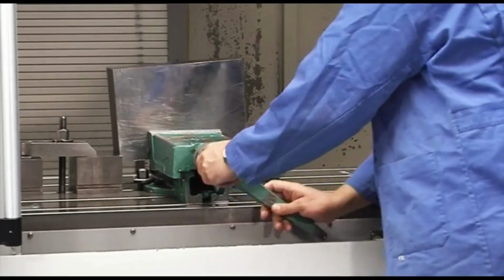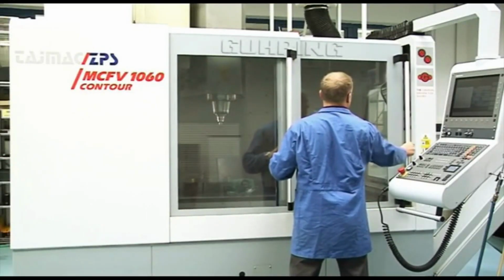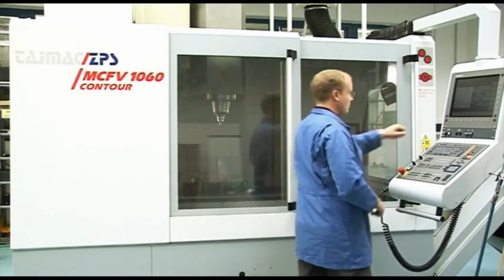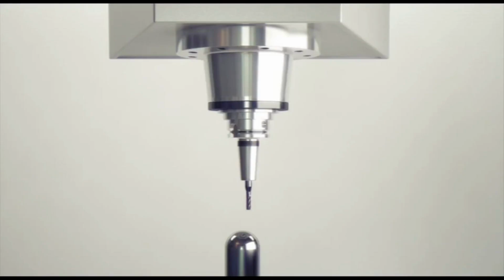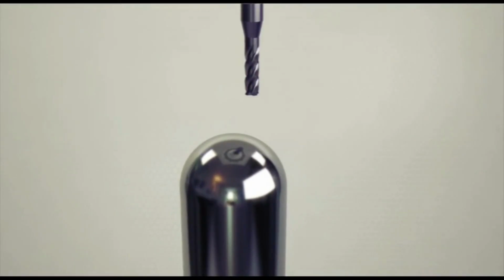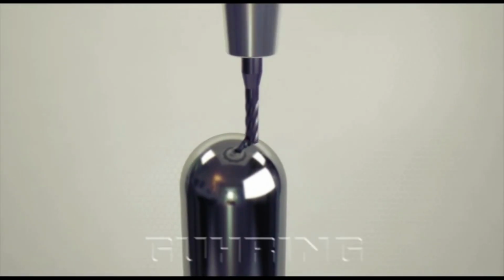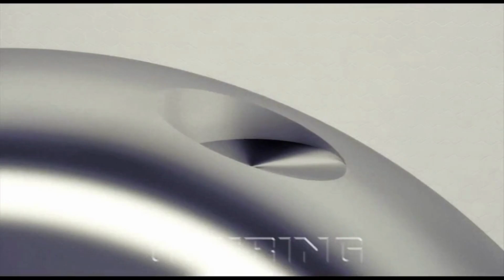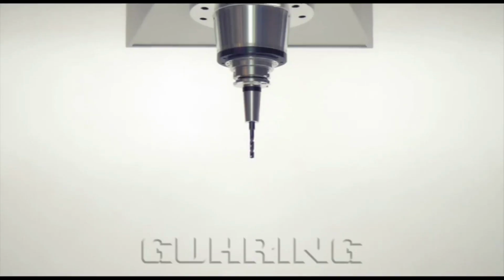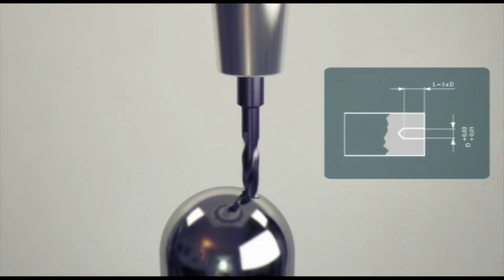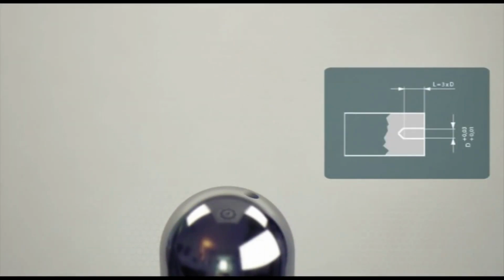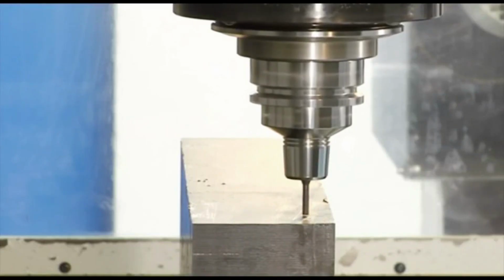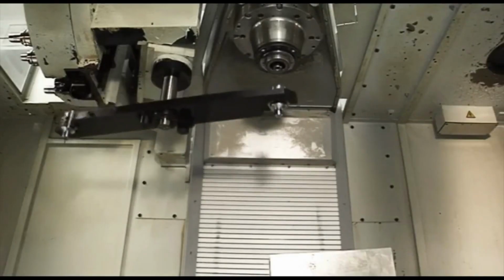Deep holes can be drilled conventionally on a CNC machining center, MC for short. For a hole to be drilled precisely, a pilot hole is required. First, the surface of the workpiece should be machined perpendicularly to the hole center line. Then, a pilot hole has to be made for startup to a drilling depth of 3 times the hole diameter. This ensures that the gun drill is guided during startup.